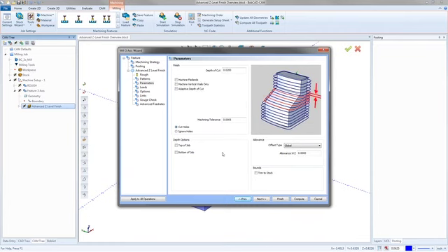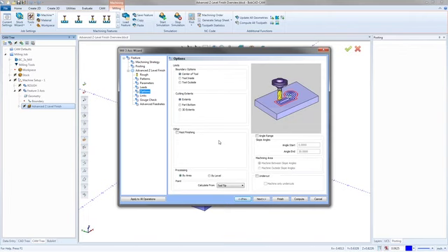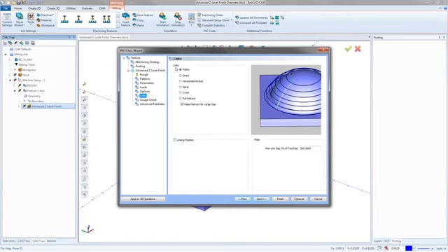I'm not going to do any of that fancy stuff. We got our top and bottom of job, our allowance, our leads, our options. Now, not too much going on in the options here. The angle range still lets you lock angles in. Undercut, we're going to look at that in 1 minute. But when we go down here, we then have our links. So this is how we connect pretty much each pass together. You've got follow, direct, horizontal, vertical. You can do a spiral, an S-link, or a full retract. Now I'm going to leave it on follow and then hit next.